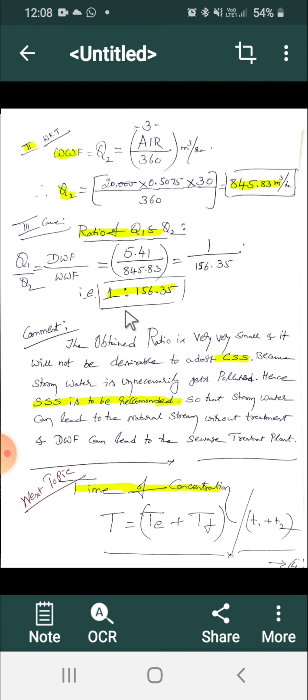And then comments. Now you observe that this is a storm water, this is sewage. These two are very different. This is far away from the source. Now this is a huge amount. If you provide a combined sewerage system, it is a difficult case, because the sewage water along with the rain water gets polluted or contaminated. You have to write these comments. Why we have to provide, what we have to provide, how we have to provide, everything is given in this.